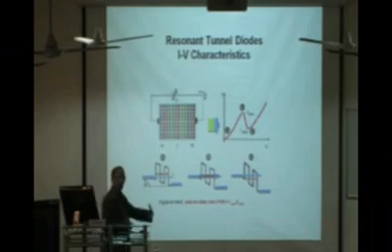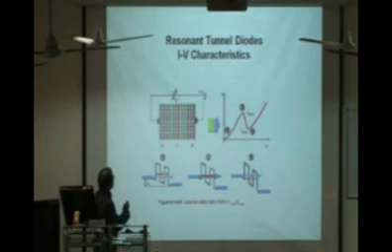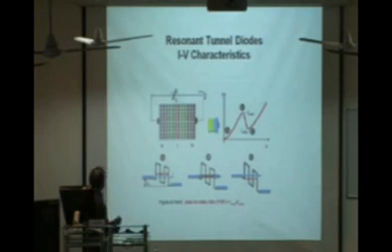As I said, one of the major candidates for making this solid state quantum computer, in addition to spintronic materials, is some kind of diodes called resonant tunneling diodes. Basically you can make transistors with a very, very small barrier between two n-type regions. This is basically a double barrier structure. One barrier is here, one barrier is here, and this is the quantum well.